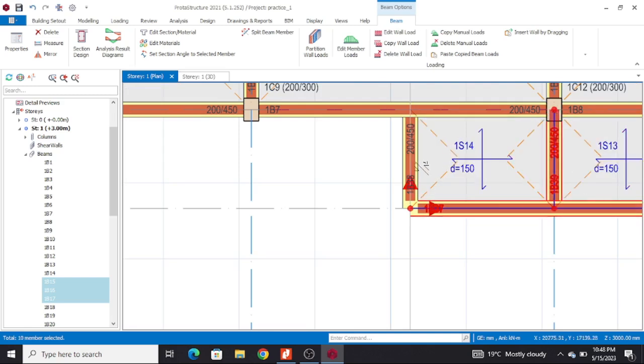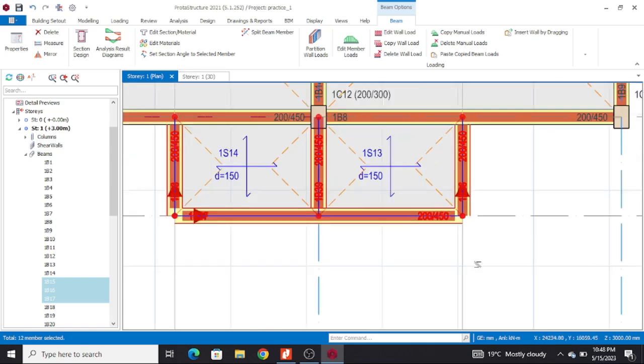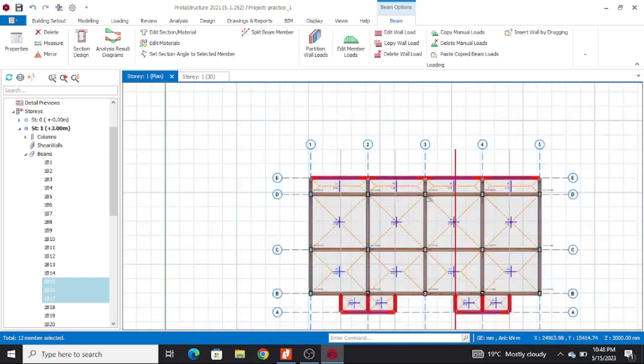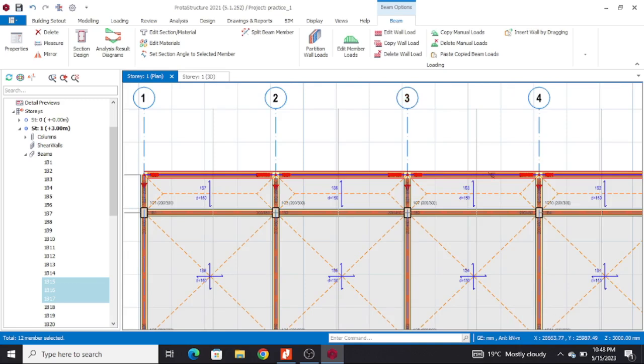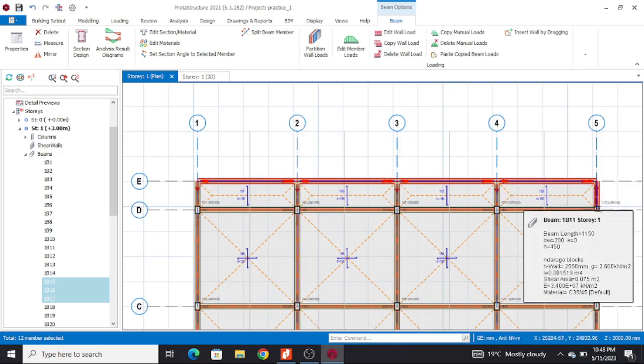All these depend on your structure, and as the civil engineer there are places where you're supposed to make a decision, because sometimes you don't have a full concrete wall here of 1 meter, you just have a parapet of maybe 200 mm, one course of masonry, and then you have steel balustrades or timber or any other barrier.